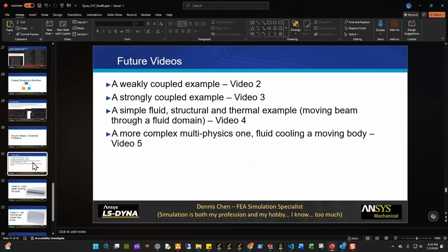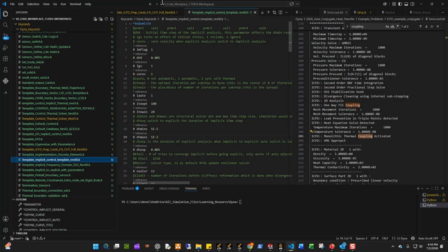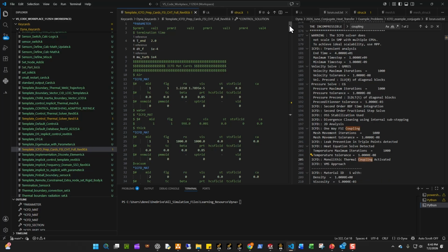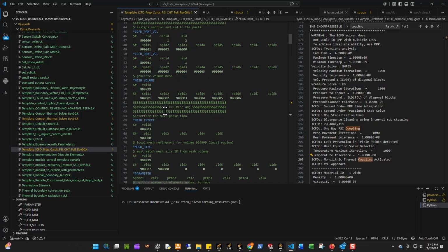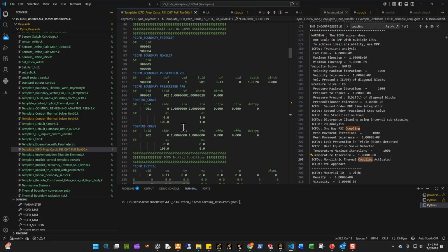All right, I'm going to share my code template with you for a second. I'm still modifying these code templates, right? Because I'm still slowly working on these things to make them better over time. But what I have here is something that you may have already seen. It's for a basic CFD, FSI, CHT problem, right? You have these standard things you have to do. You have your CFD parts, CFD volume. You have your CFD mesh, which is your boundary layers and definitions, and so on and so forth.